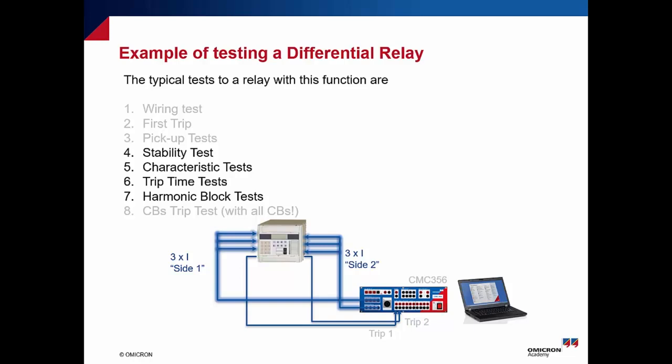Don't waste your time, and from the beginning you can consider that this relay is defective and not continue for the following points. Point number three is a backup test, which can also be considered to check the sensitivity of that relay, the minimum current. If you remember, I differential greater can be used as a parameter setting to check pickup and dropoff,